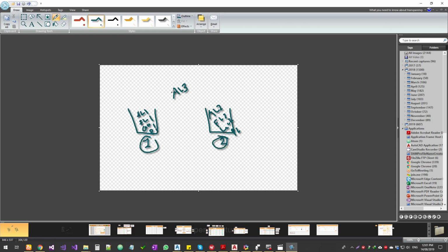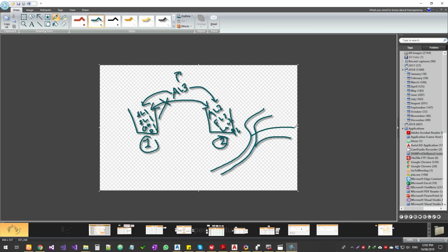The thing is, the object which is outside of a site can interact with all the objects within all the sites, and objects without any sites as well. Objects within sites cannot see objects in the other sites. So that way, if you're drawing a road, let's say there is an option for the same road to go this way, this is option 1 and option 2.